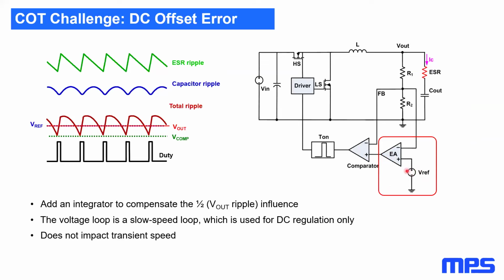The reference voltage is sort of fed forward from the feedback, and through this error amplifier we can reduce the reference down to this compensation value, sort of equivalent to the one we saw before with the peak current mode control. So we're effectively reducing the reference voltage and therefore making sure we eliminate the DC offset, basically.